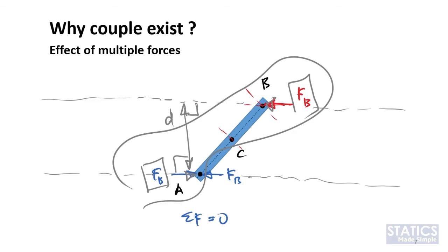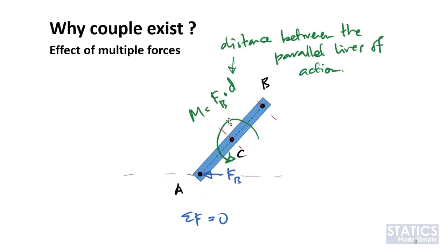Don't tell me the distance should be at an angle of beta between the lines. This doesn't make sense. Normally when we say distance, it should be this one, which is 90 degrees with respect to the lines. This one is not the right distance. So we know this moment is a free couple, the couple or free moment. It is not acting at A or B. It is acting everywhere, for the whole rigid body.